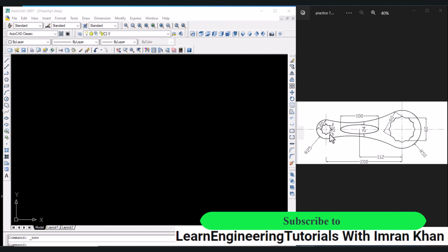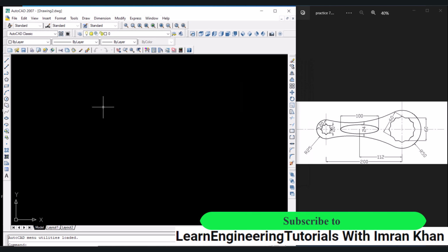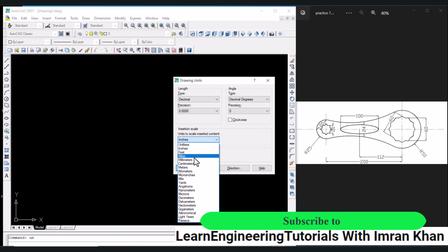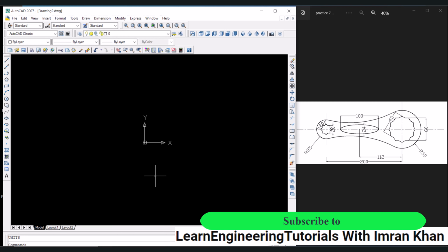So now for this second object, click on new file, double click on AutoCAD, set the units by typing UN, enter, and selecting the units as millimeter. Click on OK. Now click on line,